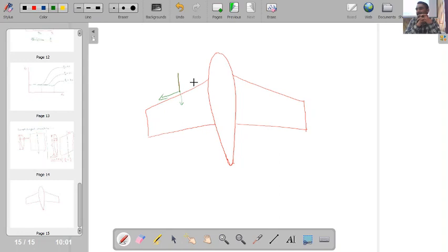If someone is interested in flight mechanics, you can go into more detail. But from the understanding of compressible flow, we can say that if we are able to maintain a thin thickness by chord ratio, then ultimately our drag divergence Mach number will become large. If that value becomes large, then I can have my free stream Mach number larger. So that is the understanding.